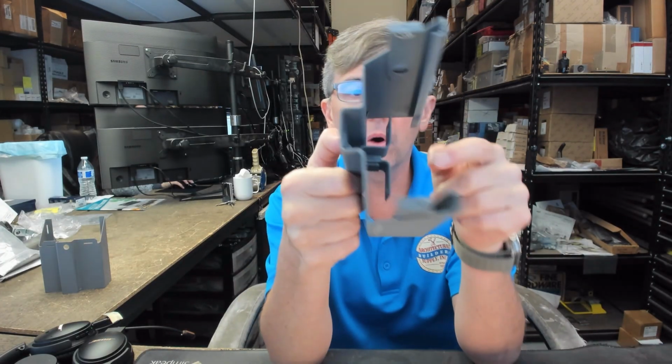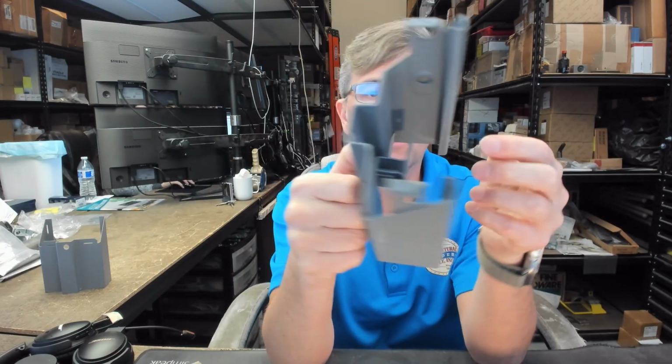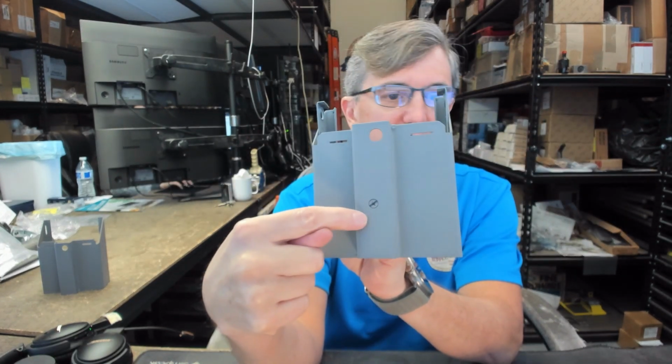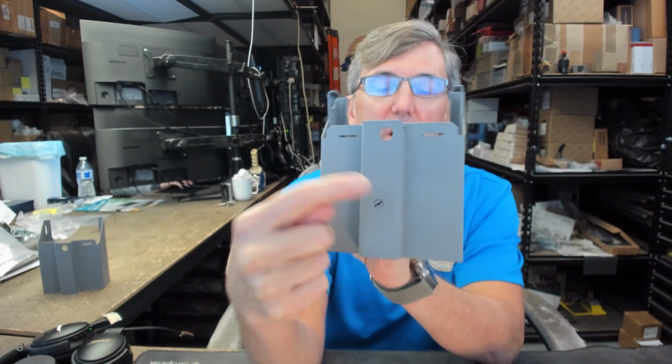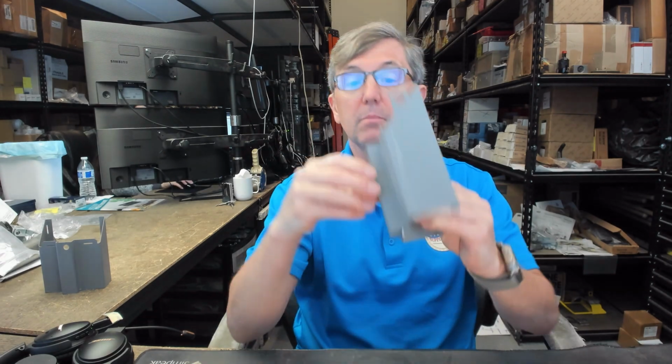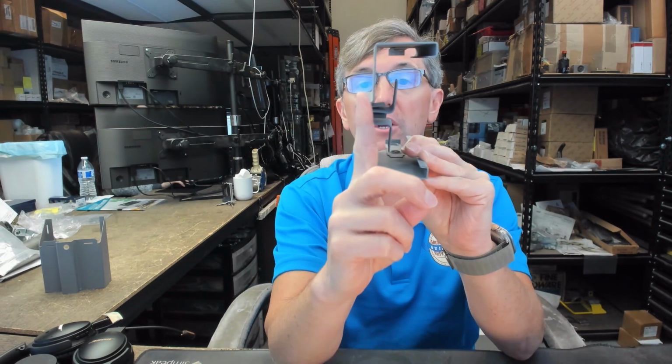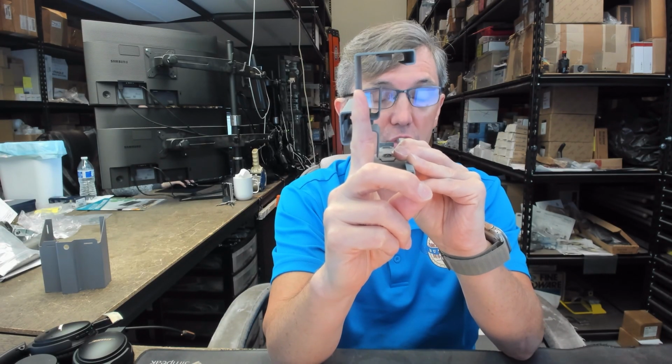Now, that rough opening is generally inherent to the concept of drywall frames. However, you'll notice this is an anchor. We're going to talk about that. This anchor is attached to the stop. In the soffit is where this screw is. That logic applies when you are working with a rabbeted frame like this. If you're working with a cased opening frame, you've just moved that anchor 5/8 closer on each side.